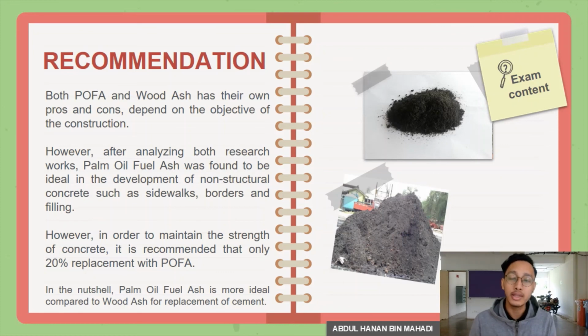However, in order to maintain the strength of concrete, it is recommended to use only 20% replacement with POFA. So, in a nutshell, palm oil fuel ash or POFA is more ideal compared to wood ash for replacement of the cement.